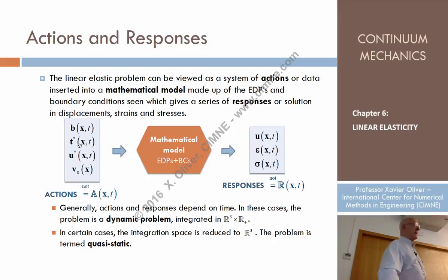For instance, if I consider this desk, if I place some force on this surface, I know that. I could place at this point some forces, some horizontal, some vertical, etc. So these also are known. The imposed displacements. Of course, we know what part of the boundary is supported or where you impose a displacement. For example, if I impose on this body a displacement, at this part here where I have my fingers, we have displacements which are zero, and at that part where I have my right hand fingers, I have a displacement which I know is imposed. It's different if I put that displacement, or if I put that displacement. That's the data of the problem.